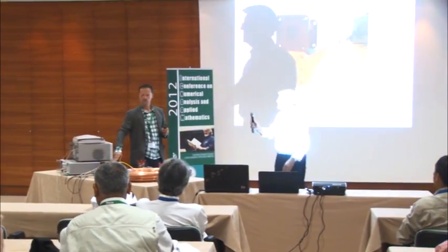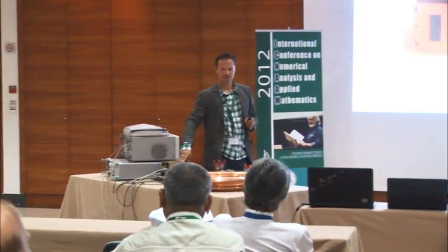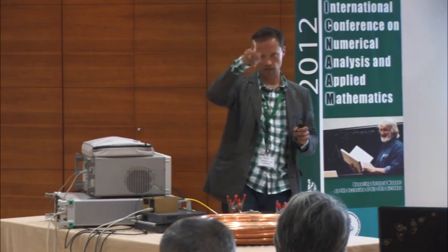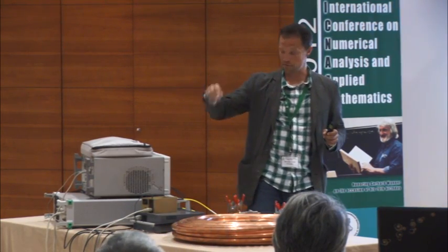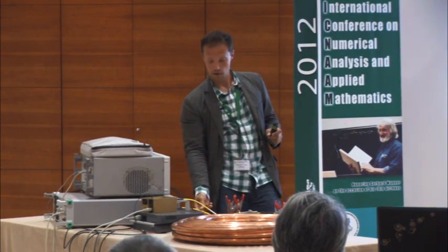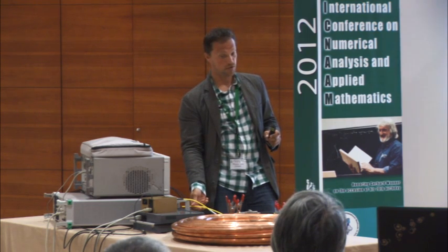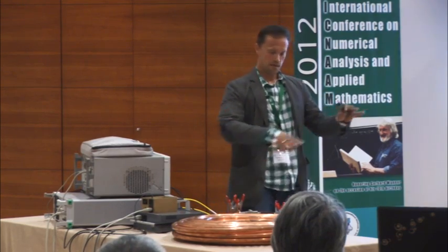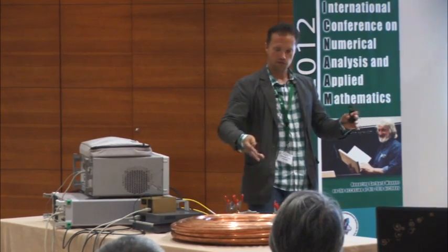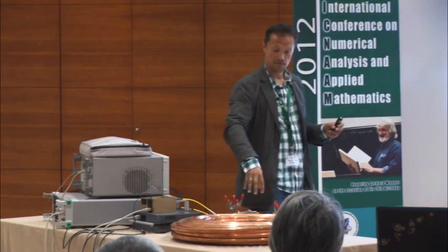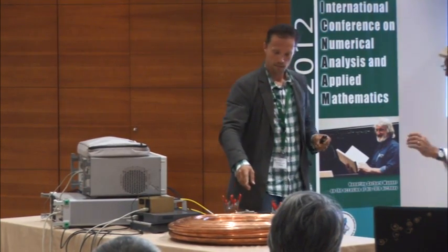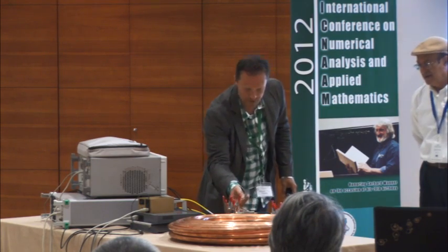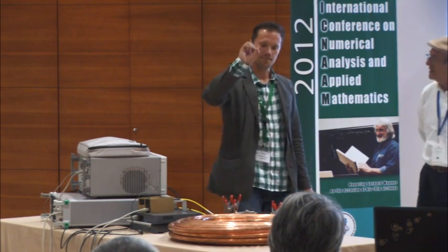So we have a signal generator, and that signal generator generates microwave at approximately 9.15 gigahertz. So it's actually a vibrating sine. That is the carrier frequency, and this carrier frequency comes out of that cable, a microwave cable, which is able to carry the frequency of 9.15 gigahertz. And now, and this is maybe what your concern is about, we have to get that frequency onto the waveguide. How do you do it? This is done via that adapter. This adapter is kind of an antenna, and this antenna